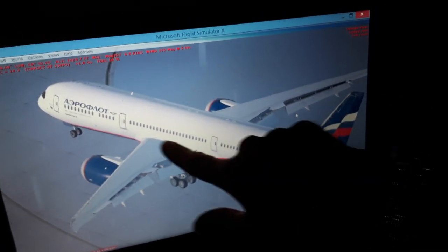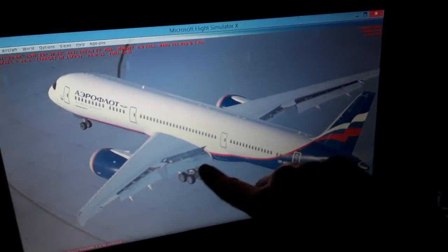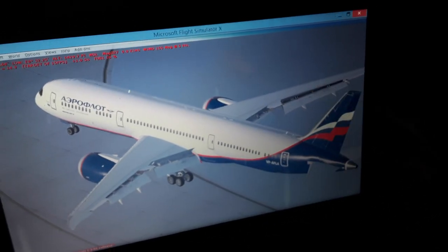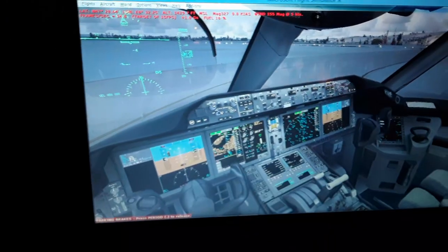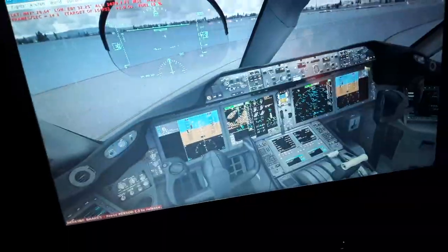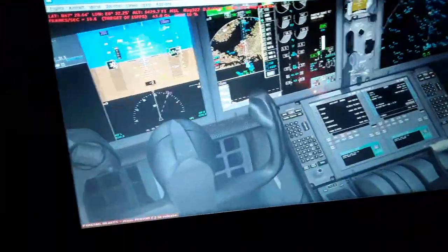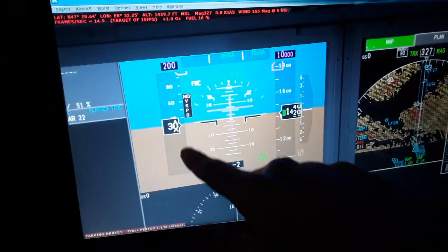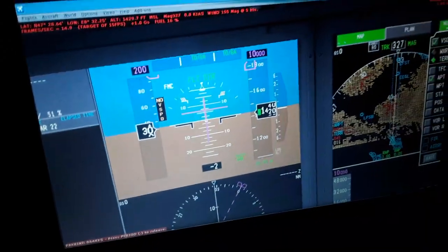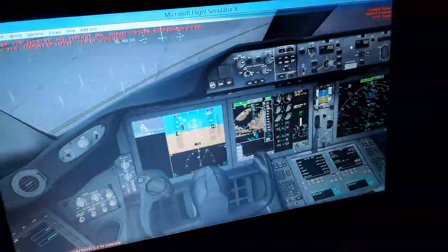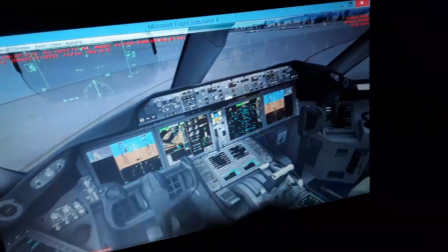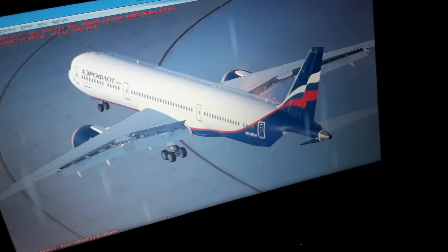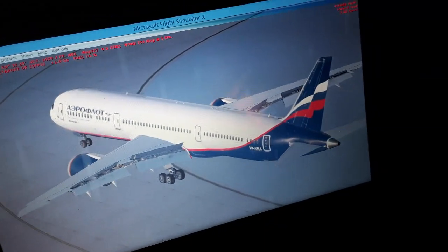Also where the stall begins, the airflow becomes detached from the top surface of the wings as we fly, and we need to pay attention. So we will stall the aircraft. We have to monitor inside here in the primary flight display. On the airspeed tape, we will see the stall speed displayed with yellow and red indication. So we need to have an airspeed above the stall speed and an angle of attack below the angle of stall.